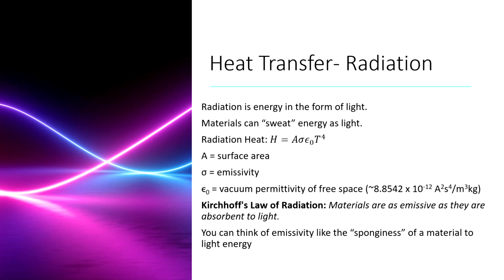But what matters here, and this is an equation that our teacher tried to show to us, is the equation for black body radiation. I'm pretty sure this is the Stefan-Boltzmann equation for black body radiation. So our rate of heat transfer depends on the surface area of whatever it is we're measuring, the emissivity of the material, whatever is on the surface usually, because you can actually coat materials like a metal plate in a paint that's more or less emissive, and that'll change how efficiently it gets rid of heat.